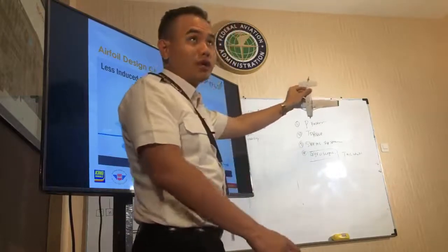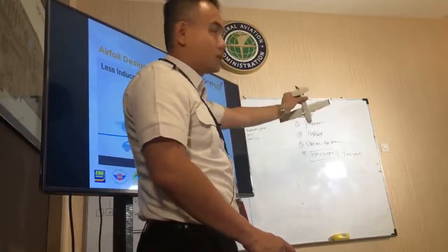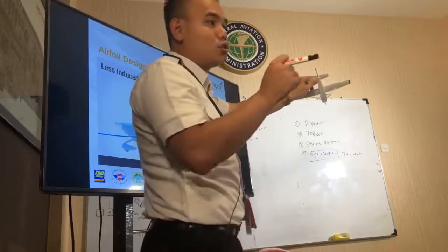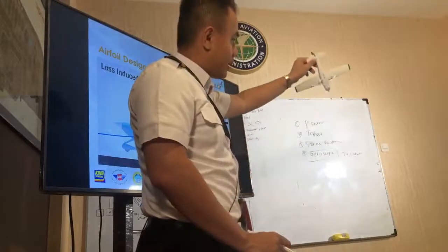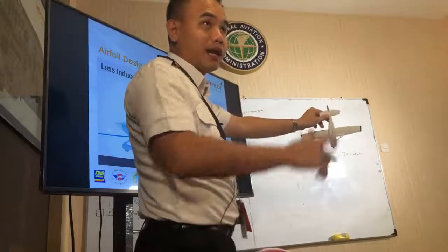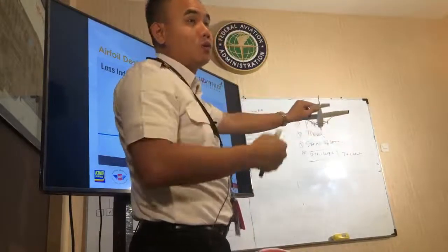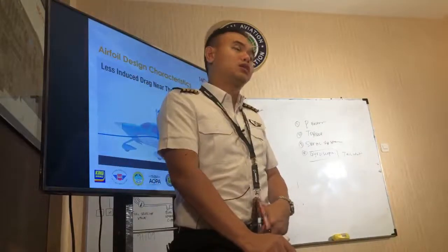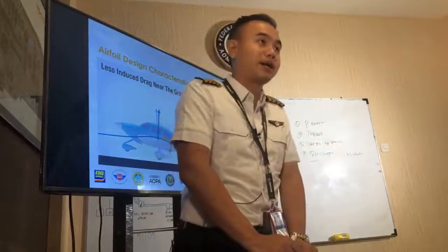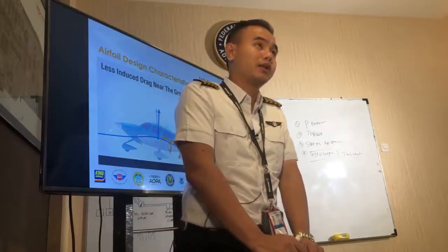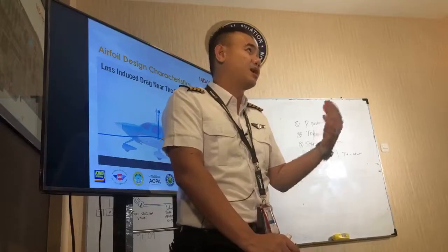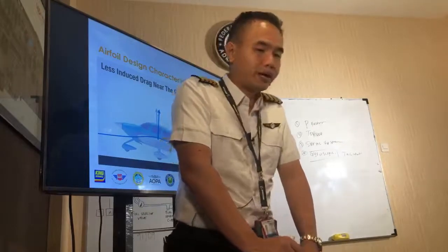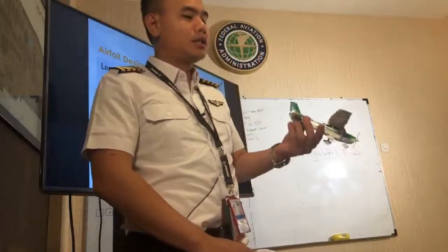I did my spin training on a Citabria. So, boom, stop, and what is the E? Elevator down. Just release to break the stall, and when the airplane is like this, getting airspeed, you then pull. And the G should not be more than 2G. The G indicator is an accelerometer. Yeah, that's the name of it. It's in the aircraft, for aerobatic airplanes, so the Citabria has one.